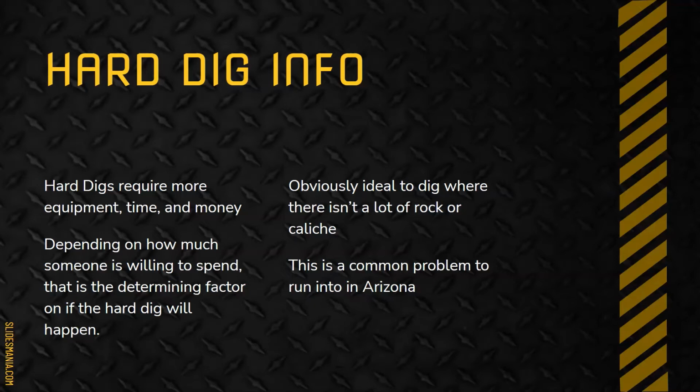So ideally, you would go into it knowing what the soil is, but unfortunately in Arizona, that's a problem. A lot of times when people are, in this case, digging a swimming pool, they run into that hard rock or caliche that prevents them from going as deep or where they need to go. So that would require a hard dig where we're bringing this heavier equipment and different people, which costs time, energy, and resources. So that essentially is what a hard dig is. And it's possible with the equipment that we have, but is less convenient than just a regular dig.